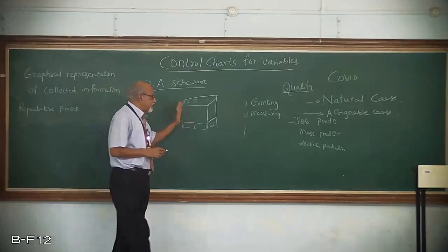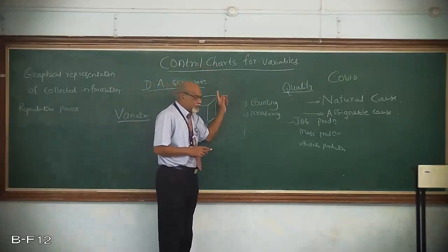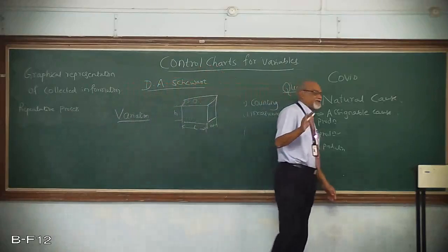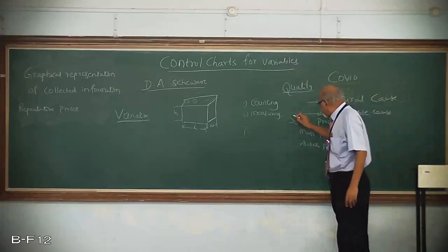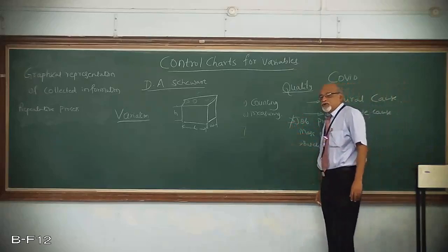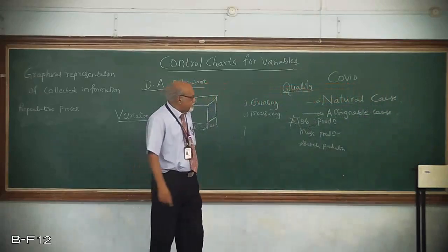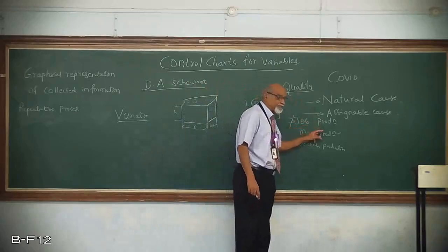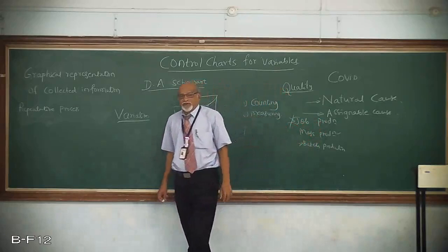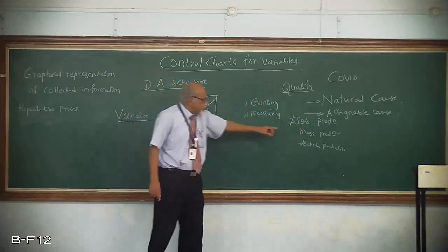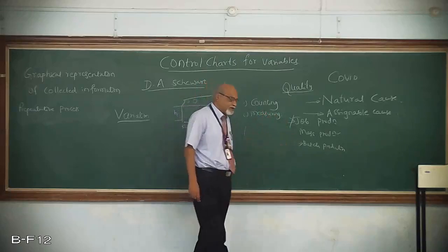So it is applicable for these control charts. They are applicable only for repetitive type of processes. That is my intention. Not for job type of production, no. It is not a repetitive process, it is one time. Whereas mass production, it is repetitive, yes, it can be applied. And it can even be applied to batch type of production. Okay, to the maximum extent in mass production, and in batch production to a limited extent.